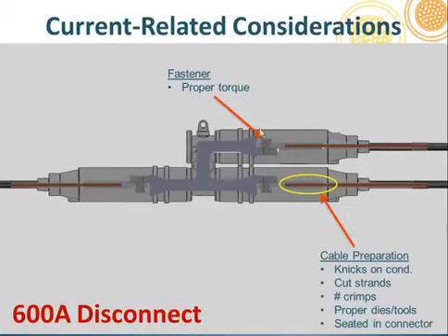There's a shear bolt head on top of this other bolt where when you torque it, you shear the head off, you know you've got the proper torque. And if you don't have the proper torque, if you don't shear the head off, you can't get the sleeve on. So it's a fail-safe system that is available in the market.